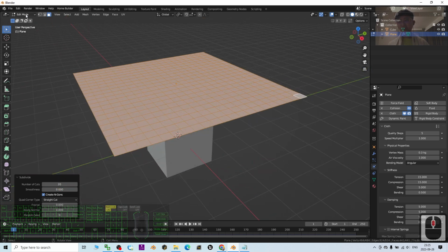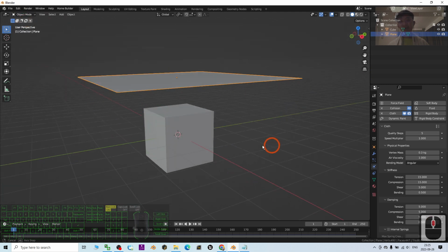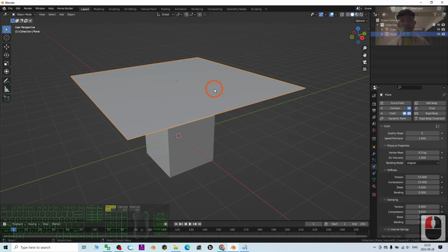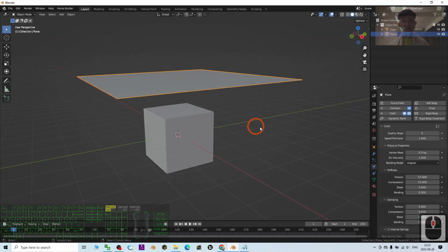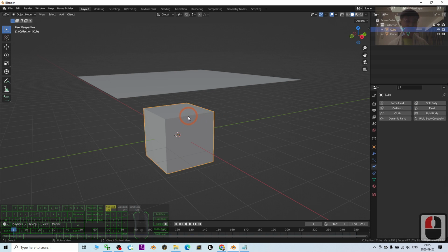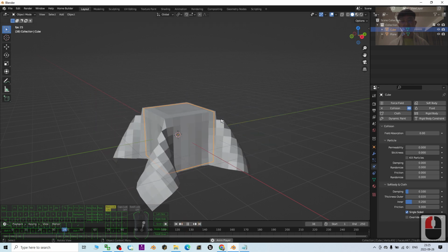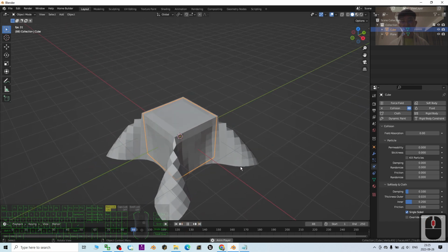Next, back to the object mode, and now I want this soft cloth to cover this cube. First, I can just click this cube. Then, at the same time, I select the physics, turn on the collision. That's all. So once I try to play, now it is going to become a soft cloth like this.